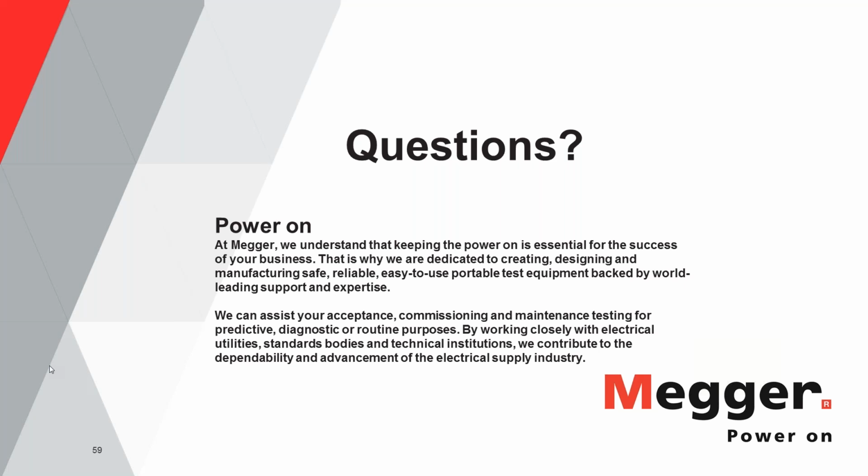Okay, thank you. Next question. How do you regulate current in real time in primary injection? If you're using a test set with traditional technology where the current control is manual, you would need to change the current in real time by changing the variac on your test set.